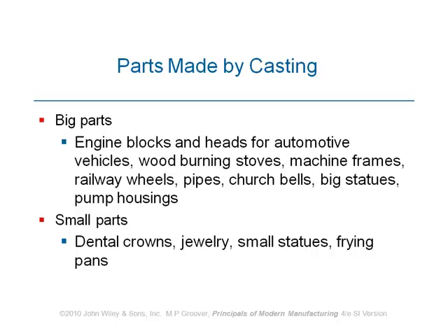Yes? What about powder metallurgy? Powder metallurgy is a different process. It's not considered a casting process, but it is very similar. As an alternative to casting? Well, it is very expensive. Powder metallurgy is a very expensive method. You can make use of it, of course, but often it is used in order to make very small size parts where we need high geometrical accuracy, which is not the case for the engine block. Okay? It is possible, but it is very expensive. So there is no justification for making use of that process in order to produce engine blocks. Okay, moving on.